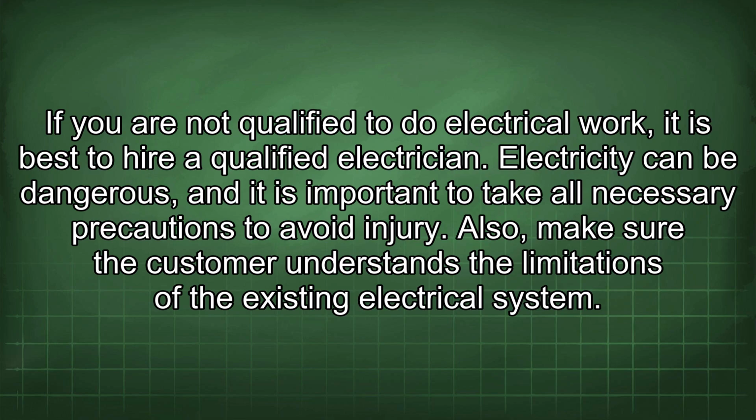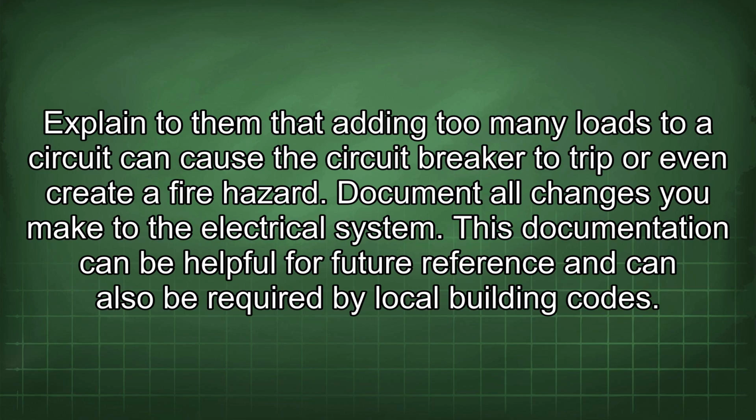Also, make sure the customer understands the limitations of the existing electrical system. Explain to them that adding too many loads to a circuit can cause a circuit breaker to trip or even create a fire hazard. Document all changes you make to the electrical system. This documentation can be helpful for future reference and can also be required by local building codes.